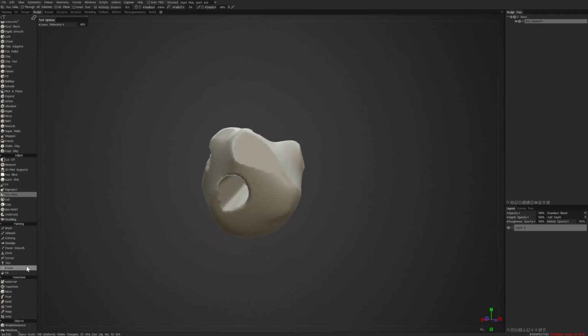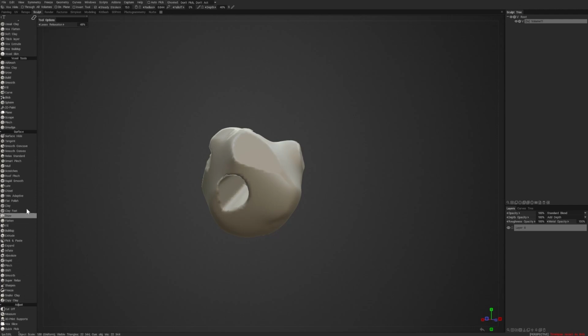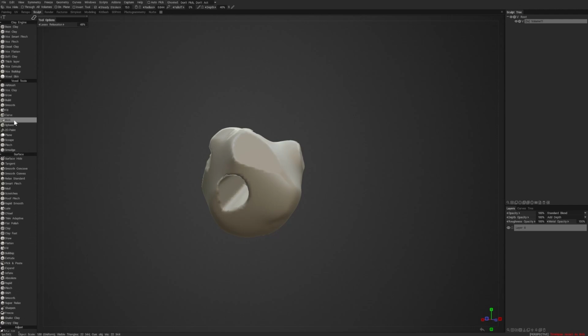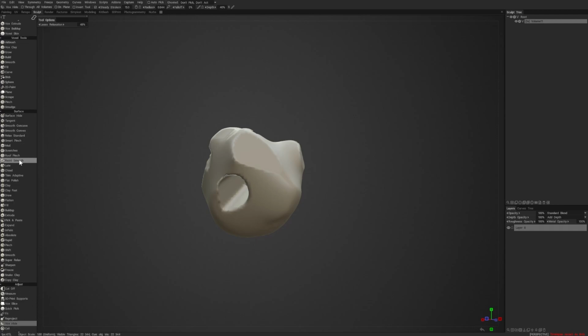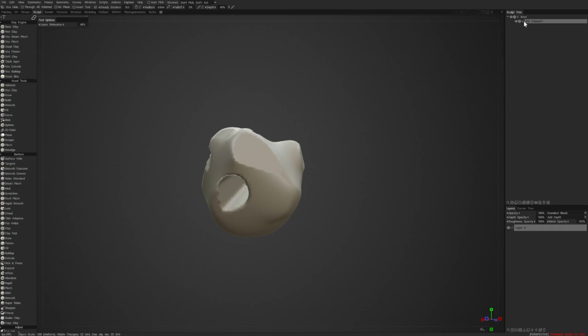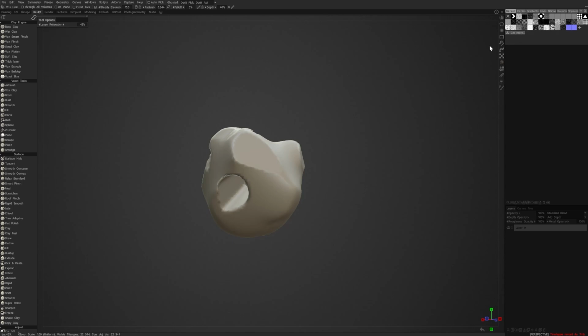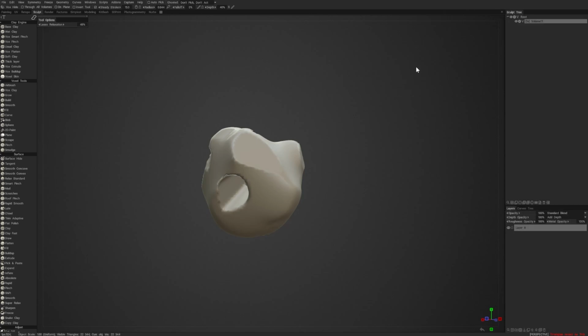A couple of the tools that I also like to use. I like to use the pinch tool. So that's under surface tools here. So while in voxel sculpting mode, and we'll talk about that in a moment, there's two different sculpt modes in 3D Coat. The most interesting and unique mode is the voxel sculpting mode, because it's not like any other sculpting application in the sense that it's effectively a 3D cloud of pixels that we can grow and shrink, and it basically dynamically remeshes those.